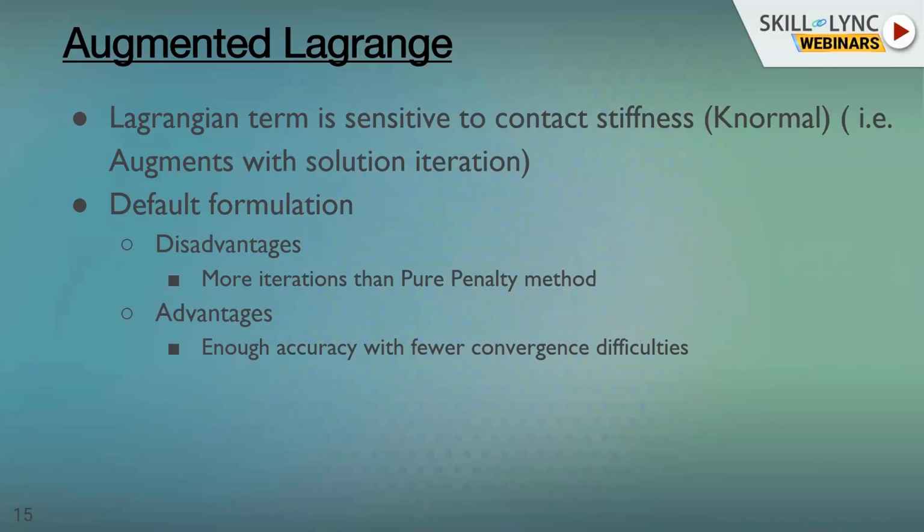If we talk about the Ansys commercial software, it is generally preferred to go ahead with augmented Lagrange in the frictional contact. In other software solutions like Radioss or Abaqus, there are two algorithms and they generally prefer the pure penalty algorithm, because their pure penalty is good enough and it doesn't allow a lot of penetration into the bodies.